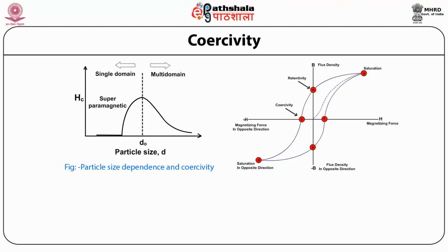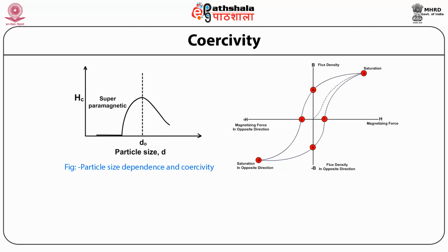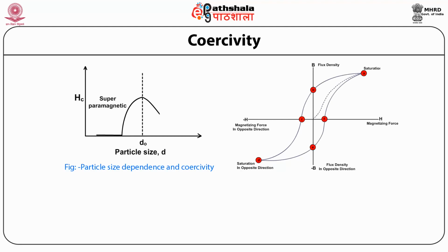Ferromagnetic materials with high coercivity are called magnetically hard materials and are used to make permanent magnets. Materials with low coercivity are said to be magnetically soft. The latter are used in transformer and inductor cores, recording heads, microwave devices, and magnetic shielding.